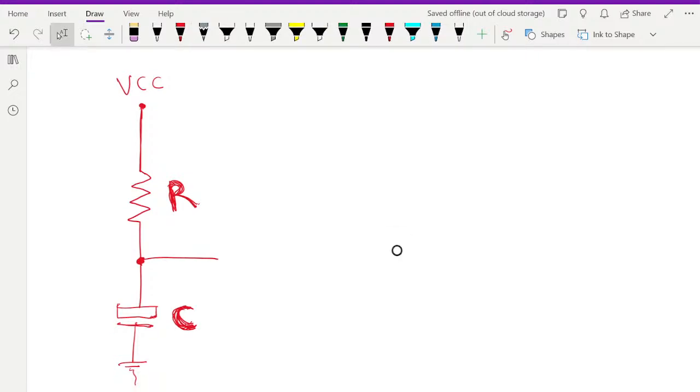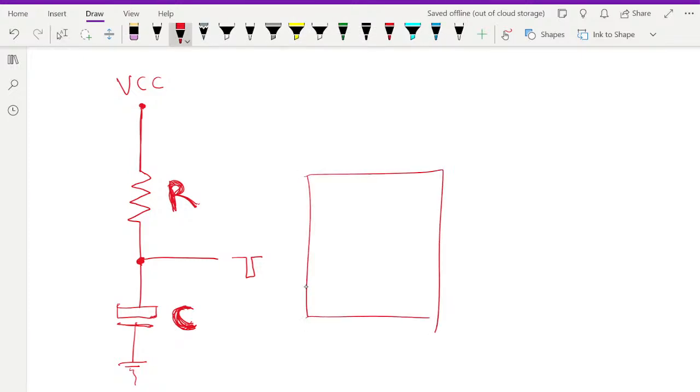Now here, once I power this up, momentarily this is going to see a low, and that is all you need to reset. So connect this to your microcontroller, whatever system you need to reset. So I'm just going to say microcontroller. So whatever you want to reset will be reset. That system needs a reset that's low going, right? So that's how you reset that.